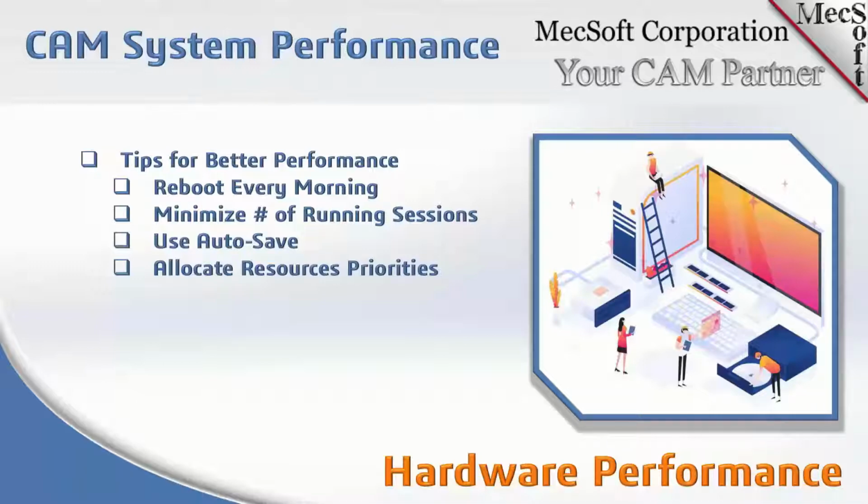And then obviously each of the CAD systems we run on have autosave options. It's a good idea to activate those. Autosave every 5 minutes or so. You may think it's an interruption, but it may actually save you a lot of time if you had a computer crash or something went wrong. And then also, we're going to show you how to allocate resources to the CAD system so that it has priority over other resources.